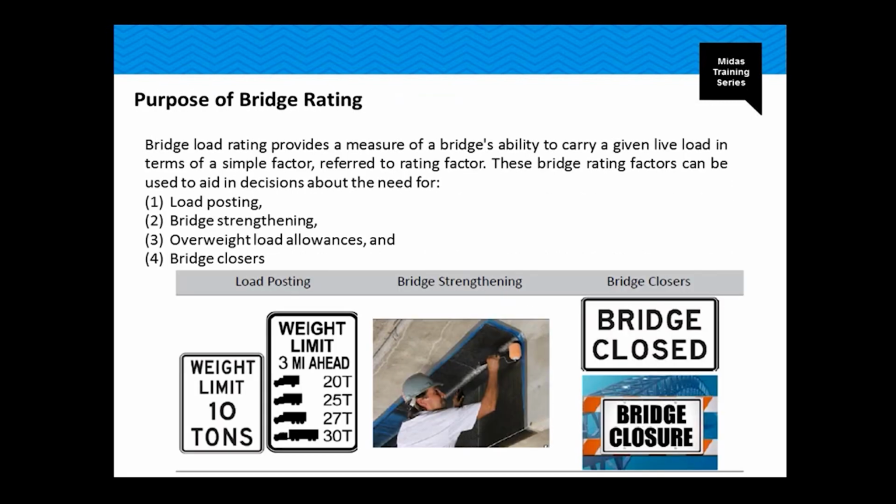The bridge load rating provides a measure of the bridge's ability to carry a given live load in terms of a simple factor, which is the rating factor that we just mentioned. They are used to help in decision making about the needs for load posting, such as here you see we can specify the limits of the weight that can pass through the bridge, or for bridge strengthening, as well as for the overweight load allowance, or for bridge closures.